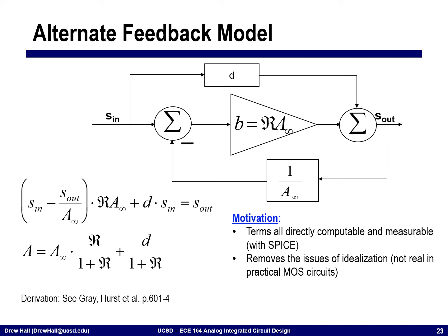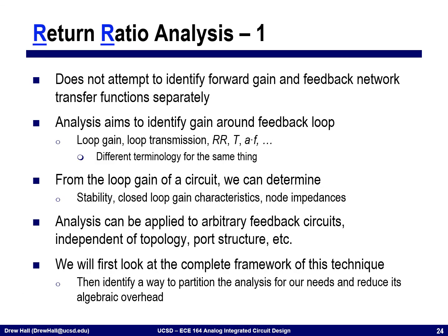And so all of this lets me do simulations in SPICE to verify my hand calculations for the closed loop gain. More importantly, I make no assumptions when I'm analyzing the circuit to try to figure out idealized portions of the circuit, i.e. this only contributes to F or this only contributes to A. I don't have to worry about the loading. This technique fits in and solves a lot of the problems that we saw with the previous approaches.